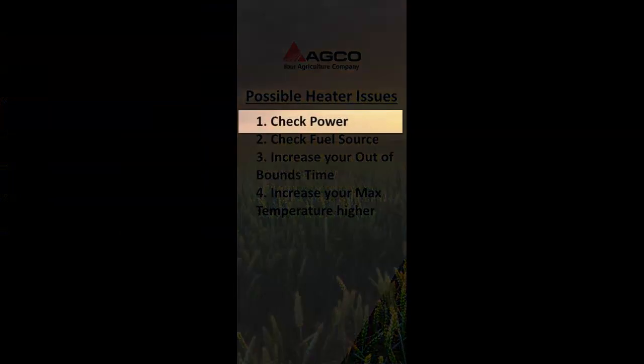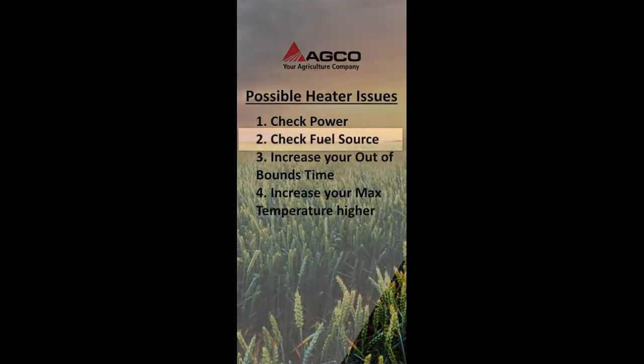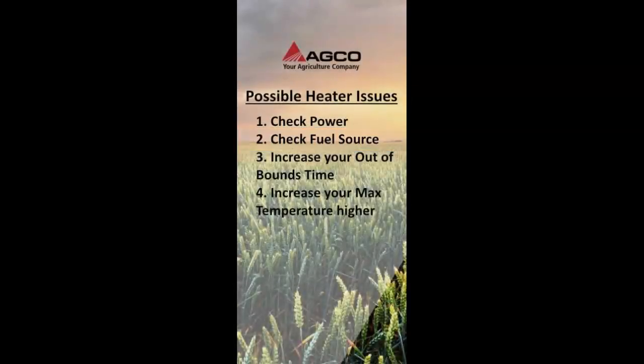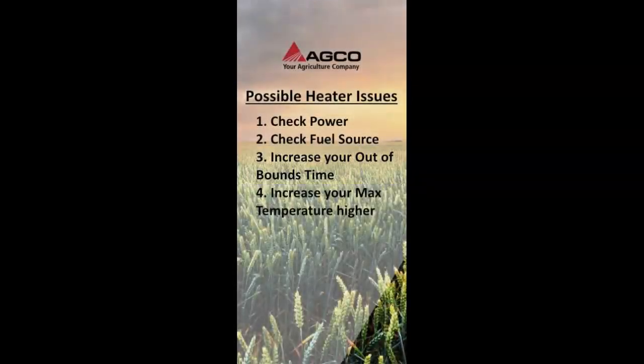1. The easiest and most common. Check power and breakers. Make sure the heater turns on manually. If it doesn't turn on manually, it won't start in automatic either. 2. Check and make sure you haven't ran out of fuel. It happens, please check it. 3. Increase your max out of bounds time. Sometimes the heater just needs a little more time to work. Check that you have plenum readings also. This is the sensor that controls the system.